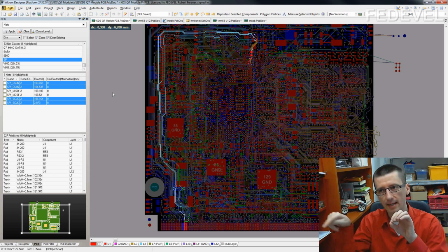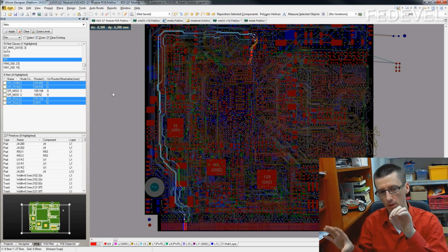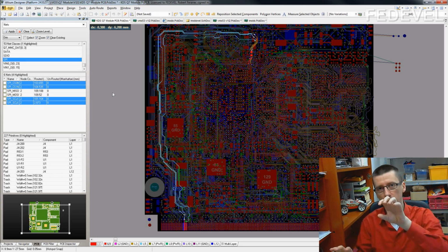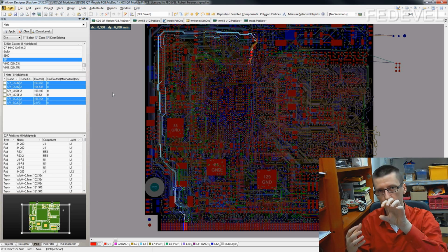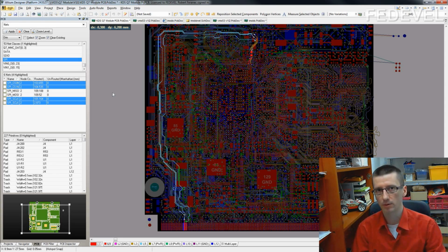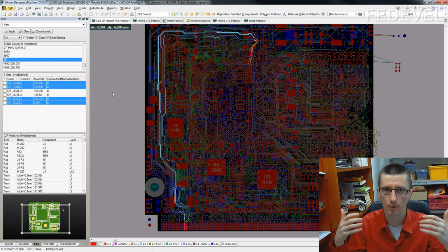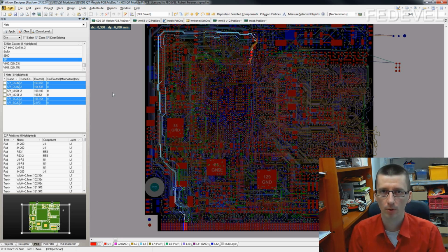So if in this area there are nets or wires which are connected to a power supply which is located here on the bottom, then the best way to connect this 3.3 volt wire is this way, because then you can connect this power supply this way. You understand where I'm going. And it's much simpler, when you use just tracks, to design these kinds of polygons or give you an idea how your future polygons will look.